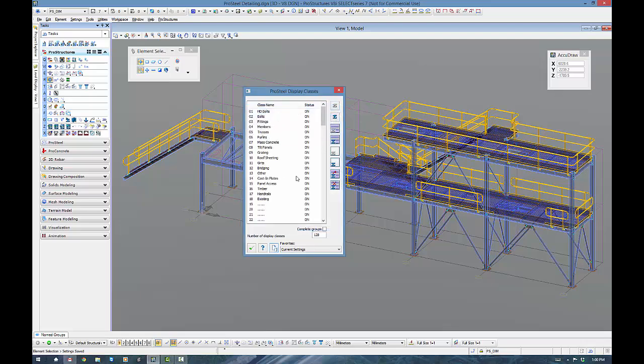Okay, and then in the Australian localization you will get exactly what I've got here, and we split apart the hold down bolt components from bolts, from fittings which are plates or flats, from members which are UB, UC, SHS, RHS, the things we want 3 views of. We can also split apart our purlins from our girts, and I've got a class here for existing steelwork, as well as other here as well, and that's for stuff that we just don't want to detail, but we needed to model to begin with.